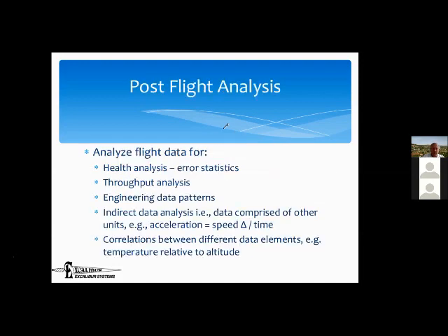Okay, another use for software in 1553 will be post-flight analysis. As you had the flight, I'm not looking for errors here. I don't need to reproduce anything here, but I do need to understand the data. Now, for this, Merlin isn't going to help, because Merlin doesn't understand much about what the data is. It's more involved in the timing and sequence of the messages at the message level, not at the data level, whereas Exalt deals more at the data level.